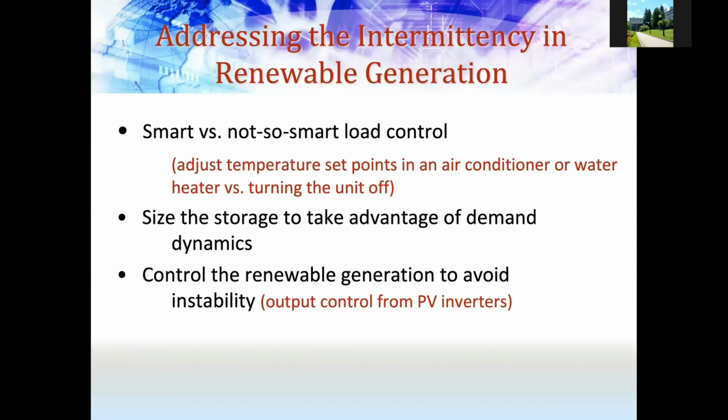Similarly, I would not use brute force to put a high amount of storage capacity in every building, it's expensive. So I would size my storage unit based on how much I cannot manage using demand dynamics. If I can manage all of it using demand dynamics, I don't need storage. So now you have the renewable generation, solar, let's say, changing. If I could adjust my load simultaneously using a smart inverter, I could manage the building. So that's what I am talking about.